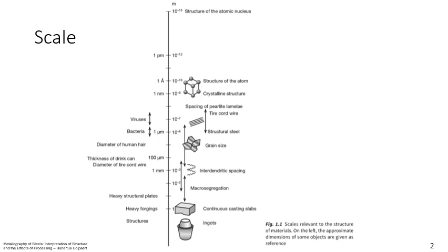for steel line pipe. We've discussed casting from the liquid to ingots or continuous casting slabs. Those are on the order of a meter or a few meters. And then we move down in size to macrosegregation, where we talked about where the elements go with respect to location in the ingot or in the continuous casting. And then we get down to a smaller size where we're discussing the dendrites, the first grains to grow from